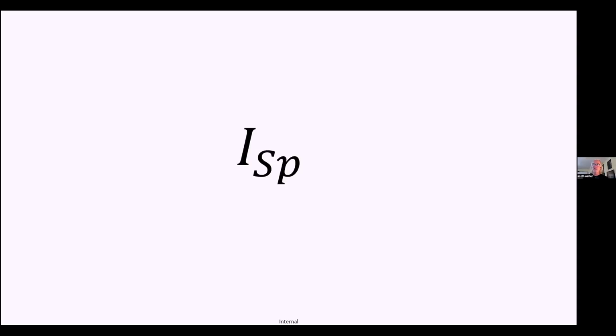Okay, John, where do we want to start? With the units, big picture. What are the units of specific impulse? We were talking about this offline, and I think the most confusing thing to people, including me, is that the units the man on the street goes by are seconds. It's weird, efficiency is in seconds. So sometimes we're used to measuring things in time that maybe shouldn't be measured in time.